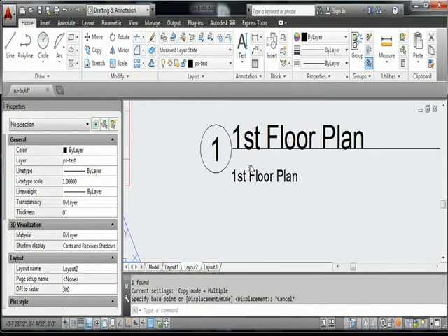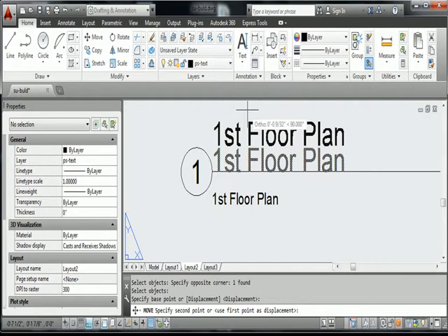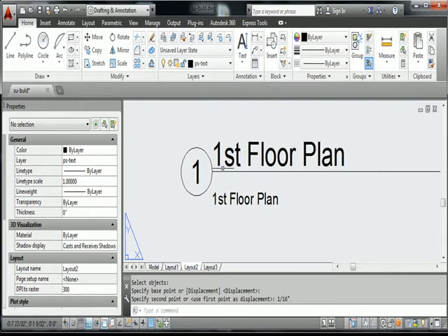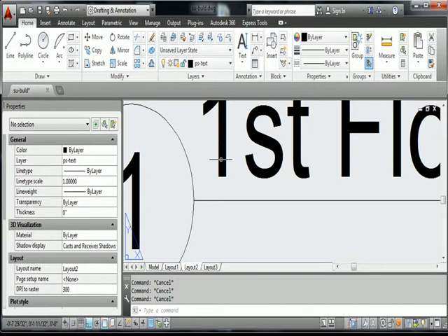So now I'm going to clean this up a little, maybe move this font up 1/16 of an inch, 1/16 of an inch up, and that looks pretty good. I might want to consider aligning this thing here. So let's say line from the insertion point up, line from the insertion point of this, which is not letting me pick it. Line INS.